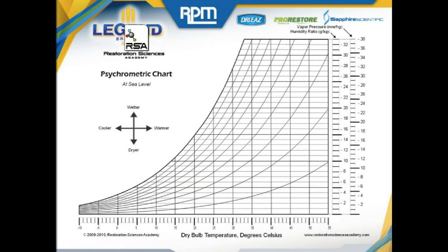Here we can see that at warm temperatures, the chart has a very high capacity for water vapor. However, as temperatures are made cooler, the chart begins to decrease in its capacity for water vapor. This is what will occur if high temperature, moisture-laden air is allowed to move towards or into cool surfaces and areas. As it loses its capacity to retain water, i.e. its energy, eventually high humidities and condensation will occur.